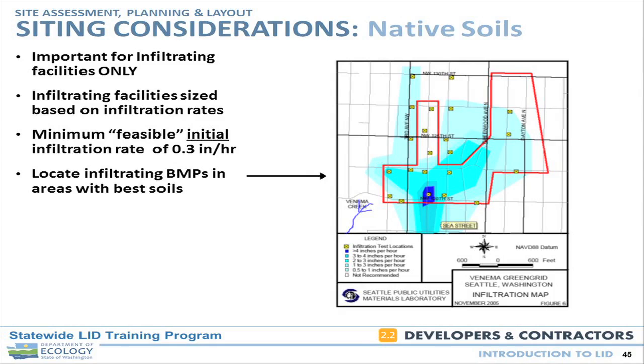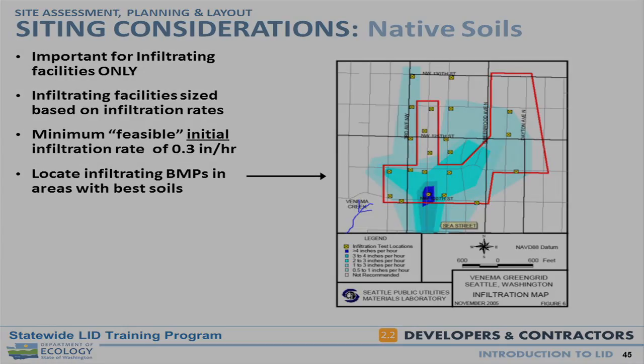The correction factors used to be basically, depending on the size of the test, if you did a relatively small-scale test, a safety factor of 4 and 2, and now there's a little more of a nuanced set of correction factors. But suffice it to say, that's the infiltration rate that they measure with the pit test in the field. And then you go back and say, if I've got a relatively small amount of contributing area, I apply these certain factors, which give you the long-term rate. And the long-term rate is the design rate. That's the rate that's expected at the end of the life of the facility, after it has a certain amount of expected clogging.